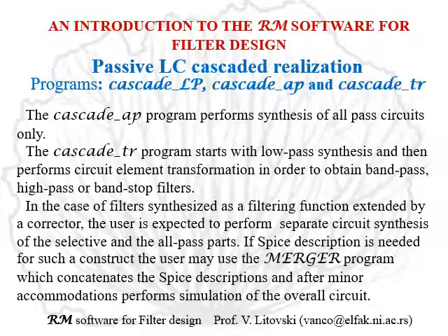The Cascade AP program performs synthesis of all-pass circuits only, and the Cascade TR program starts with a low-pass synthesis and then performs circuit element transformation based on the proper transformation which is given for the frequency domain, in order to obtain bandpass, high-pass, or bandstop filters.